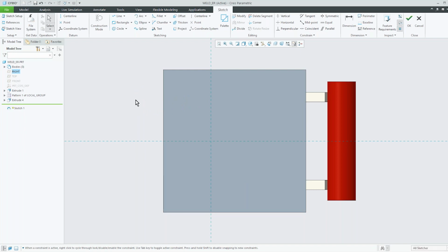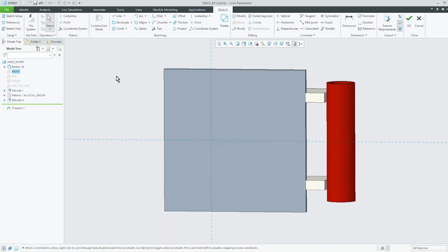Now, just a little tip from me to you about doing this. It was snapping to things that were kind of bothering me. One of the things I'll do is turn the view a little bit, and then if I start sketching, you'll notice that it doesn't snap to anything behind here, even though I have it turned on, right? It'll tell me when I'm perpendicular or hitting one of my references, but it doesn't see the lines behind here, even though that is turned on. So bringing it out of being planar to the screen is one way of doing that.